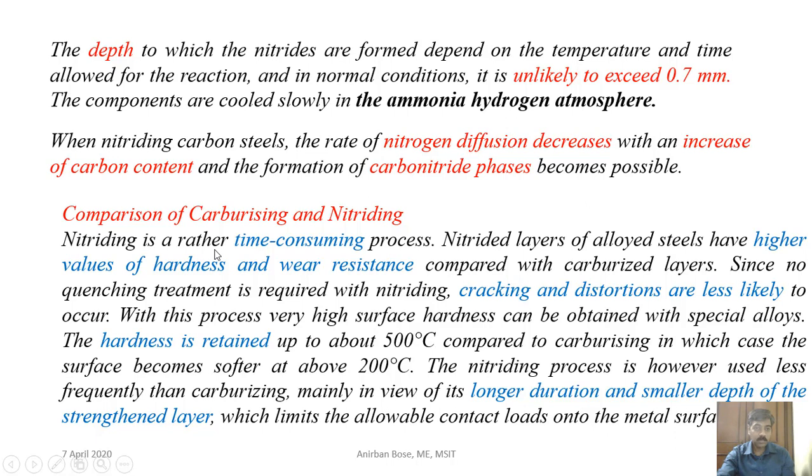What are the other comparisons we can make with the carburizing process? Obviously nitriding is a time consuming process. Higher values of hardness and wear resistance can be produced by nitriding. That is a very important point. And not only that, cracking and distortions are less likely in the nitriding process, because there is no quenching occurring here. That is why the cracking and distortions are less likely.